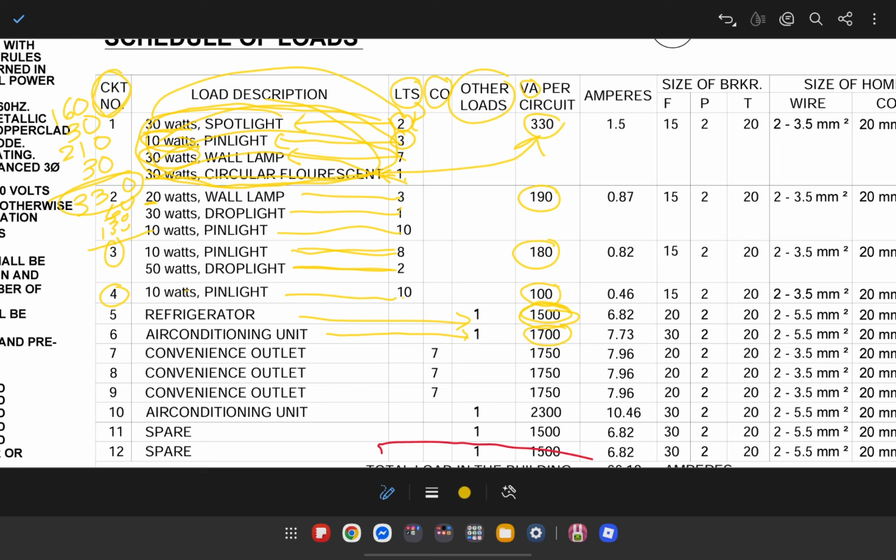What we are familiar with are the horsepowers. The horsepower or the sizing of the aircon would depend on the use of the room, the number of occupants, the size of the glass window, if it is with curtain, if it is exposed to the outdoor, or the height of the room, the headroom clearance, etc. So there are so many things that we need to consider when we do the sizing of the air conditioning unit.